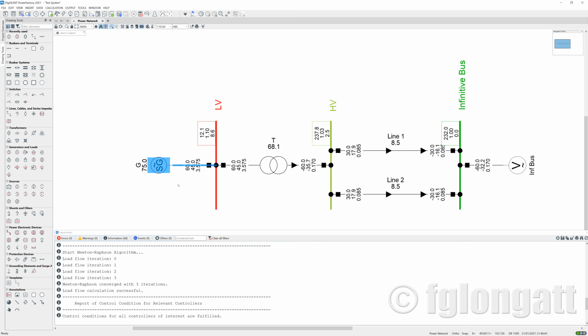reactive power. And because we are producing so much reactive power, you can see from here they are departing 45 MVR, and from there it's reaching here 32.2 MVR. Okay, what I'm telling you is right now the reactive power flow is changing. The direction of the reactive power flow is changing because we are producing so much reactive power.